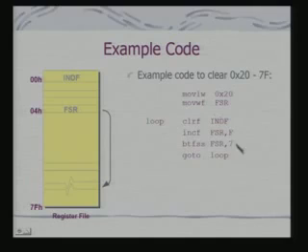As you go through the loop, what are we checking here? This will do a skip when it is set. So, this loop will not be executed when you have reached 7F. If you are trying to increment beyond 7F, you will skip, otherwise you will be clearing the content from 20 to 7F location. This is an example of using indirect addressing.